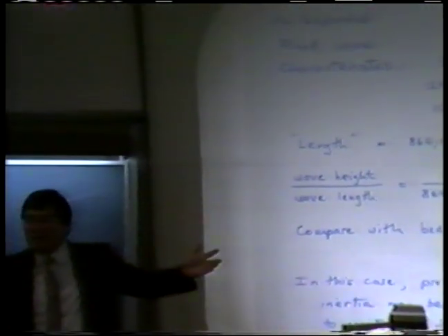But let's assume for the moment that we can talk about a time base of a certain flood. And let's say it is going to be 24 hours. Not unreasonable. It's a small watershed, though. It couldn't be too big. Those of you that work with the lower Mississippi, when the flood goes up, it takes, what, a couple months to come down?